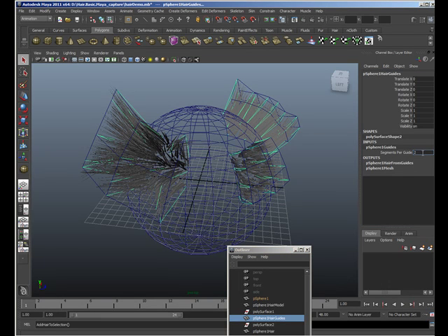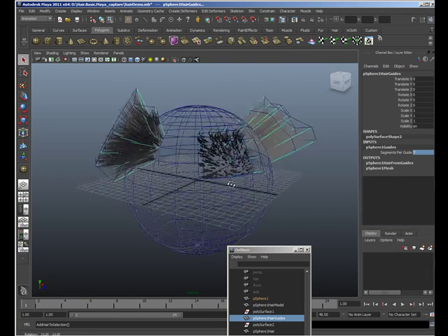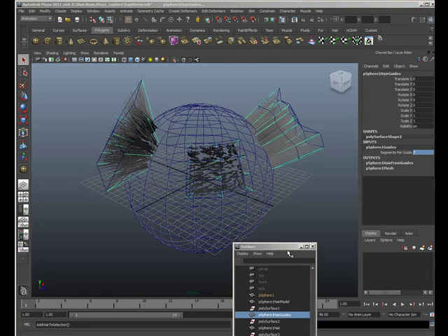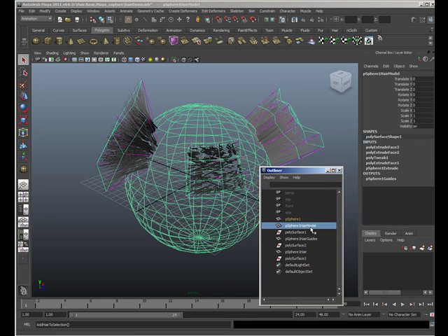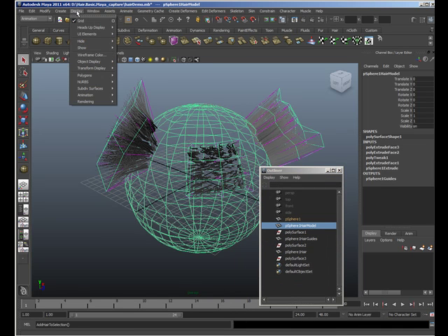We can see the segments per guide parameter. This controls how smooth the resulting guides and hairs get generated by setting the number of points along their length. The hair model mesh is the one we just modeled, and so we can hide it for now.